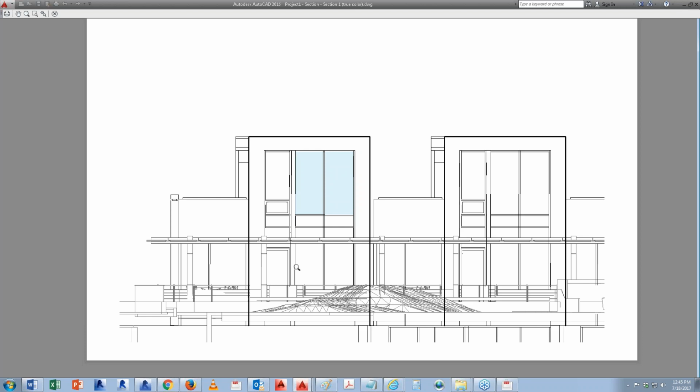So it really depends on what you're using. Both are applicable. But if you are doing, let's say, a CA, and then you want to use AutoCAD just to do check printing and all that stuff, I would recommend using true color because what you see is what you get, and then when you export it out, you see exactly what Revit sees. No one has to interpret it.